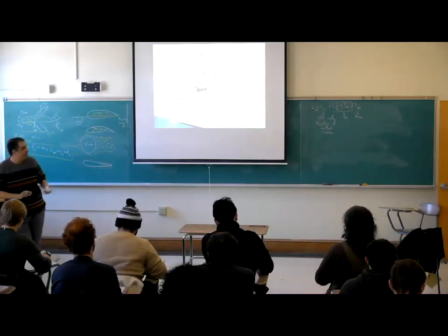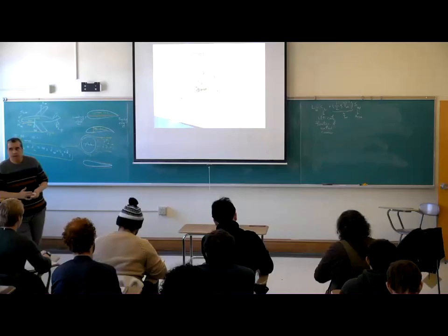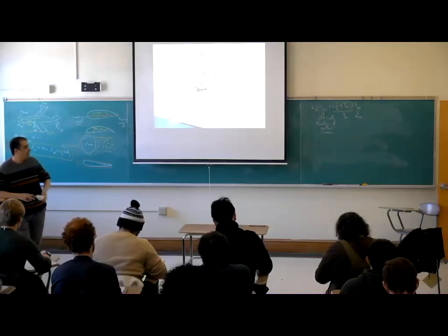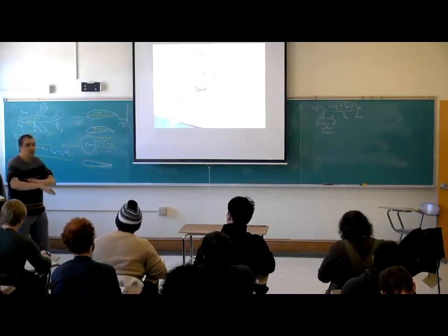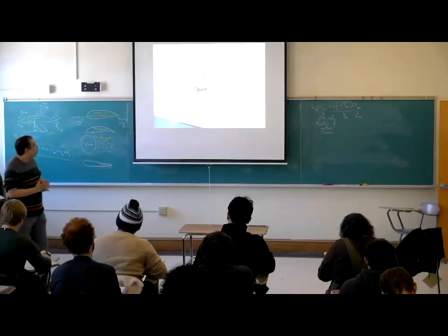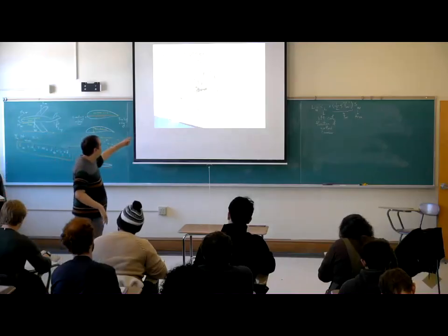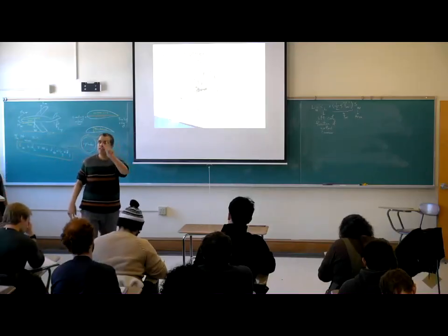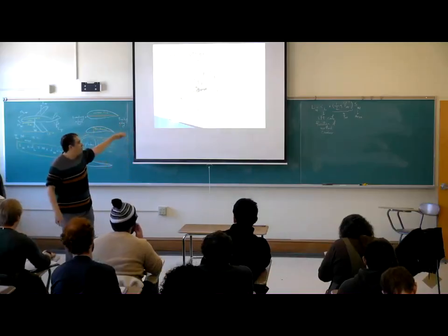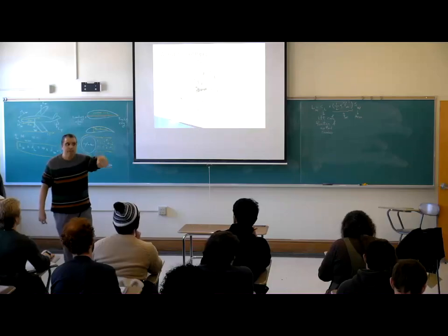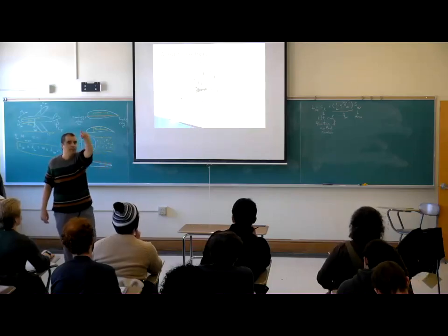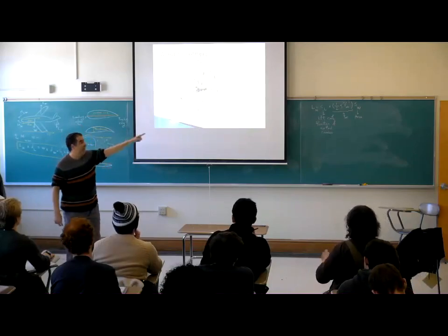The Wright brothers, if they wanted a higher lift, needed a bigger wing, which meant more weight, more drag, fabrication limitations, and many more problems. So for that, they used two wings. What is good about using two wings? What is doubled in the equation? Yes, area. S is doubled.